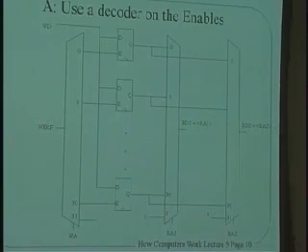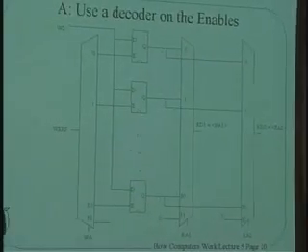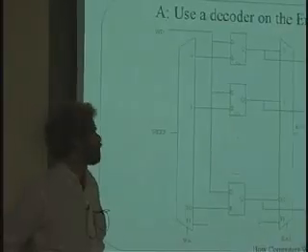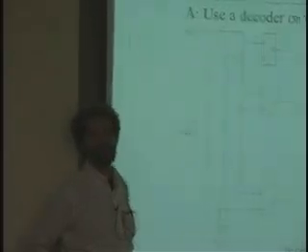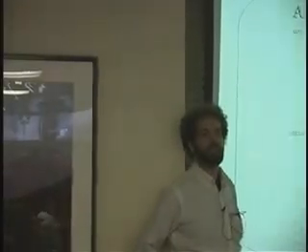So if you go through the different opcodes that we went through, you'll see that in some of the cases, WRF was set to 0. And in those cases, the idea is that the register file is told, don't write. How is that different from having the work be 1 on the register? It's exactly the same. But sometimes we're using the bits for register C for some other reason. And so I think that you'll find when you look at the code that there's some of those cases where we want WRF to, in fact, be 0 because we're using those bits for some other thing.